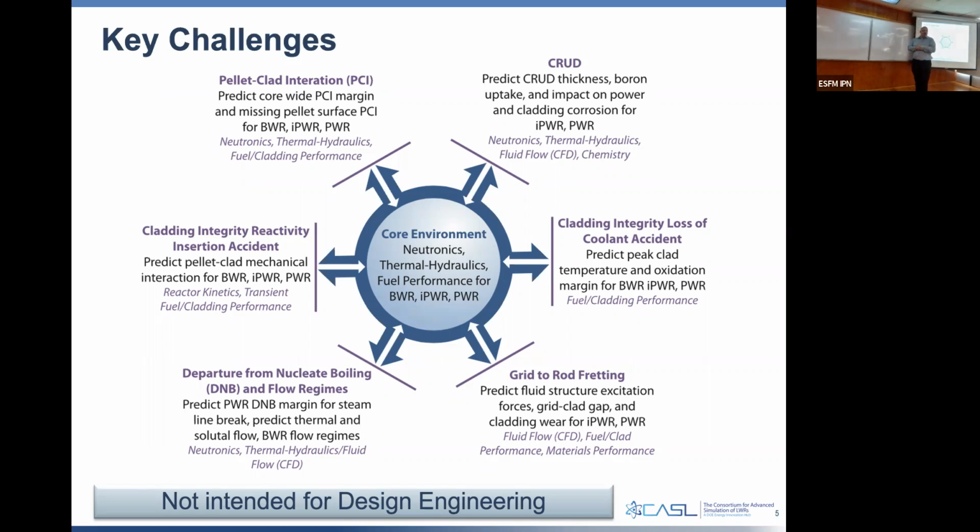There are a few utilities in the US that are doing this right now. And at times they are doing it in a way that we go down to 20% power and stay for 2 weeks and then come back up. And at times we're going within the day. We may go from 100 to 80% to 100 to 60 back to 100, just changing it throughout the day, trying to figure out how they can operate. But when they're doing that, fundamentally, they need to be able to go as quickly up and down as they can. Otherwise, they are wasting a whole lot of electricity that they could be generating and producing for the market.